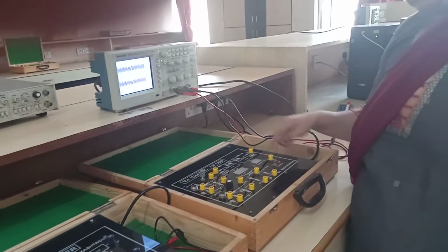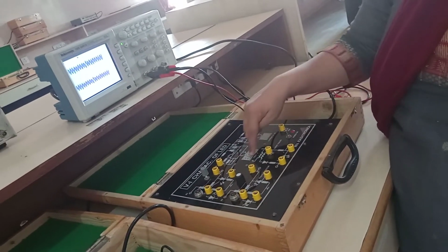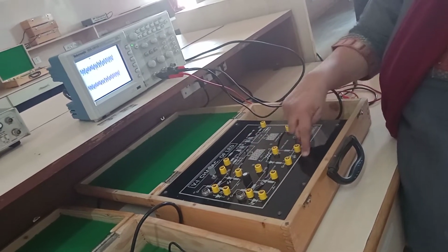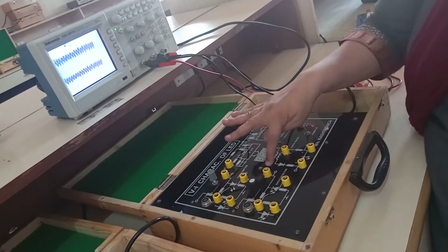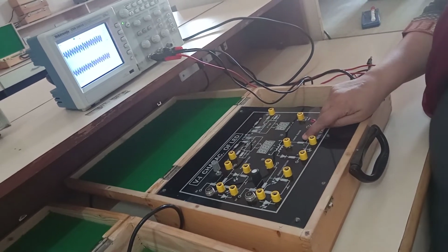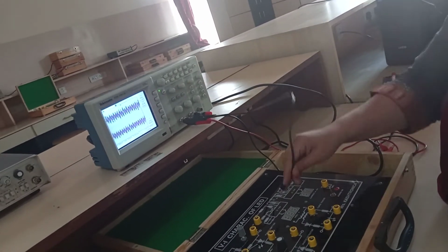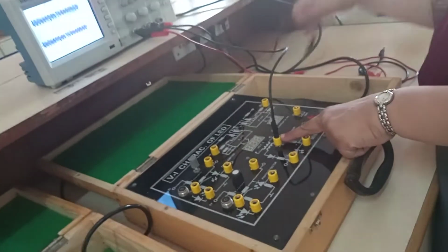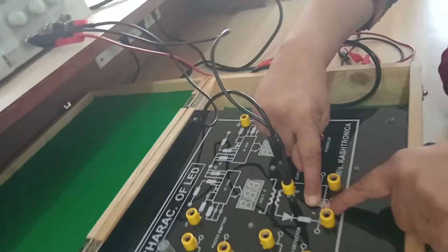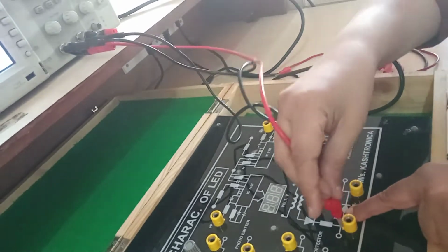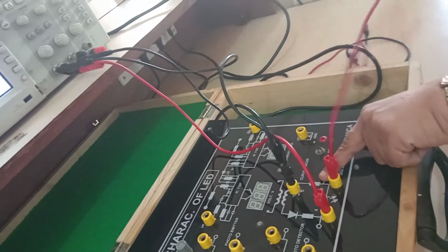Now we are supposed to test both the LEDs. For that we are supposed to use this curve tracer part. As I told you, these LEDs are not connected in the board. We are supposed to test it. So this is a curve tracer LED. For that you need to adjust the DSO. These are the ground lines. This is a ground pin of the DSO. See, X is written over here, so that is channel 1. Another, Y is written over here, so this is Y.